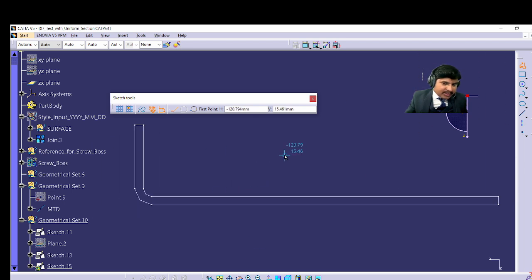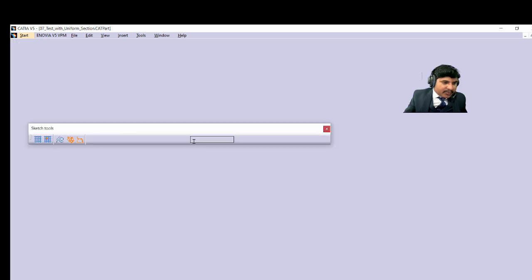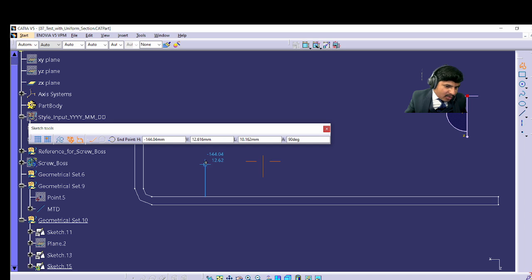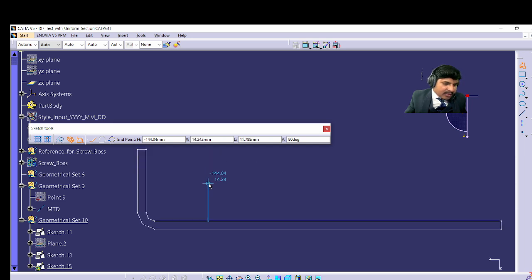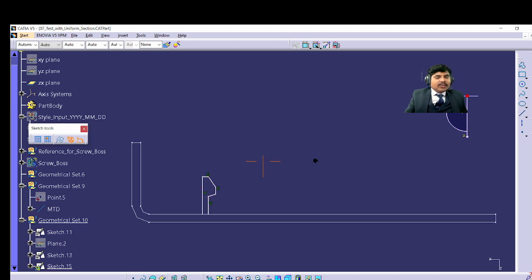So to start drawing the features, you have to start with the profile, then directly make one vertical line. Before that, in this window you have to see by how much dimension you are going upward, because if you do not follow the dimensions, then constraining is too difficult. Okay, so now I come to this, then take it approximately like this, then like this, then this one is your engaging angle, and then connect this. So this one is the feature.